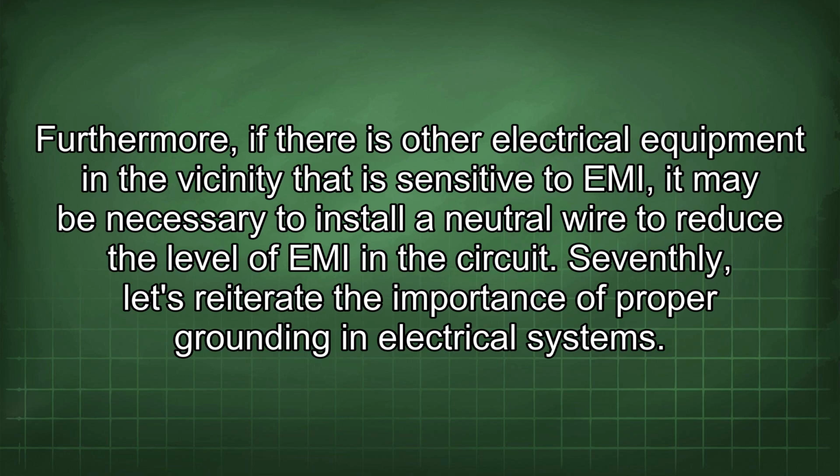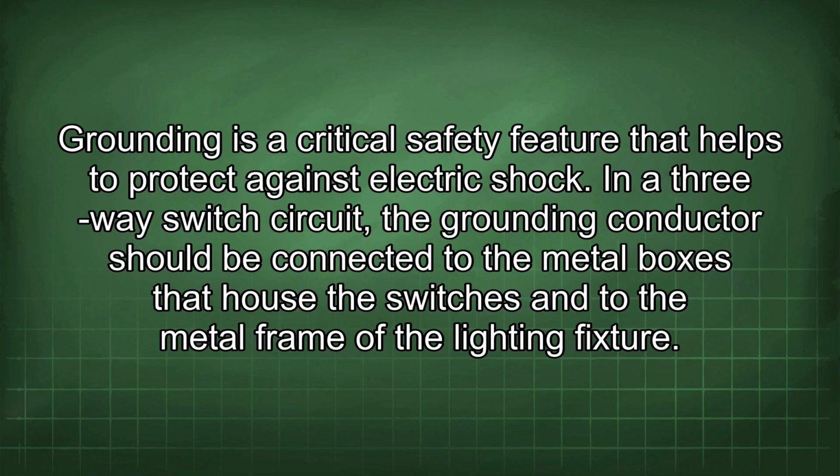Seventhly, let's reiterate the importance of proper grounding in electrical systems. Grounding is a critical safety feature that helps to protect against electric shock. In a three-way switch circuit, the grounding conductor should be connected to the metal boxes that house the switches and to the metal frame of the lighting fixture.